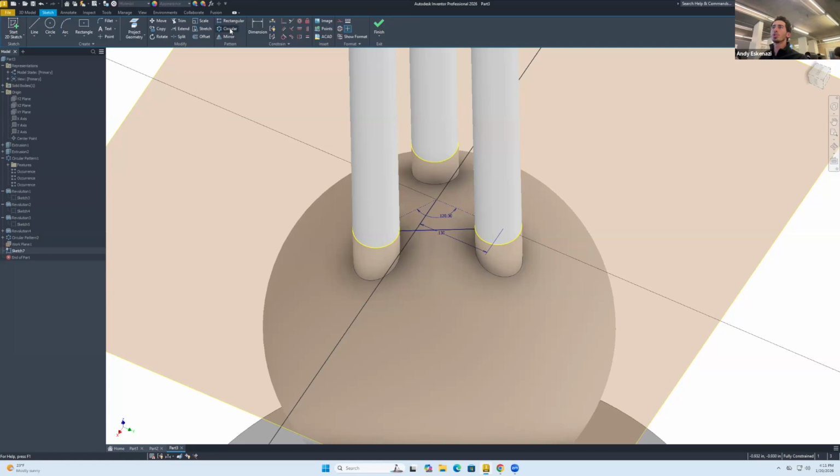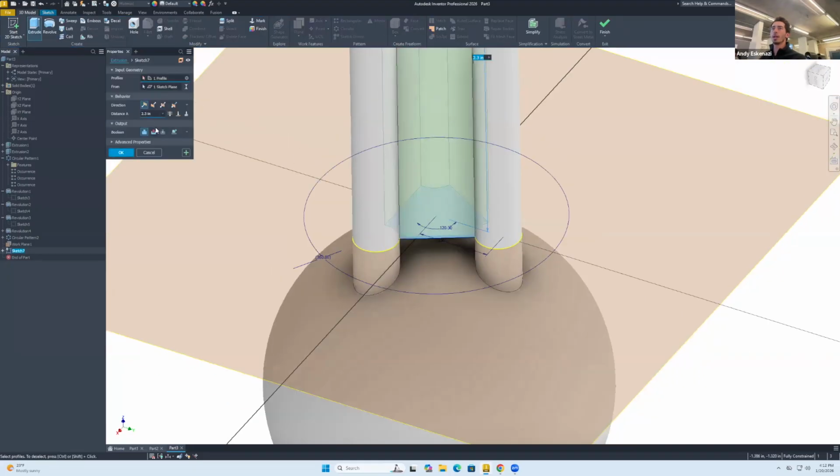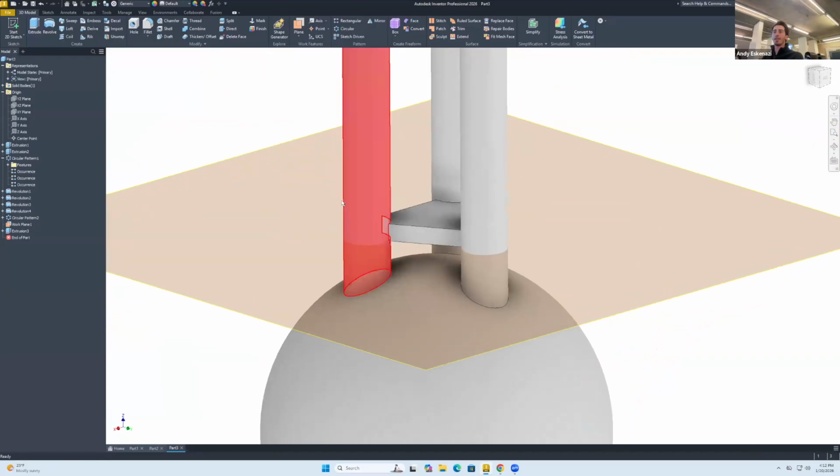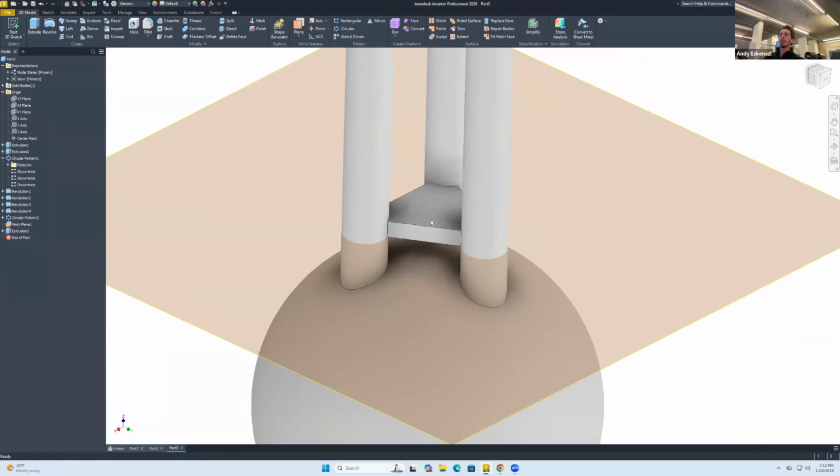And we can go over to, where are you? Circular pattern, geometry, that line, and then axis, that point, and we're gonna make 3. I go to OK, and then I can go to 3D model, and I'm gonna extrude that by 0.05. Actually, maybe less, 0.03. So now I have like one of those levels.